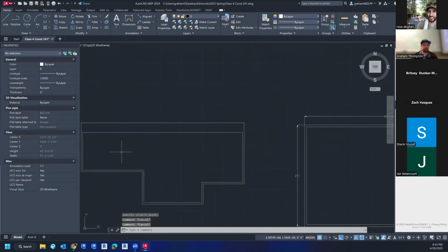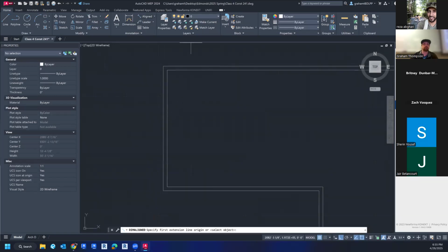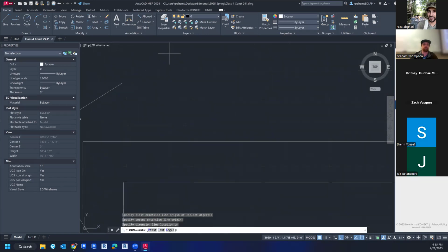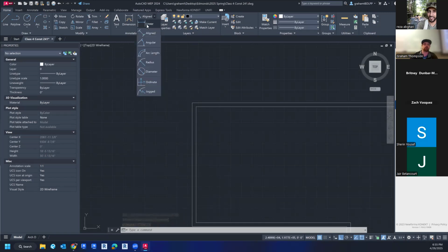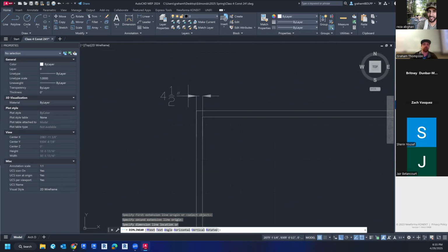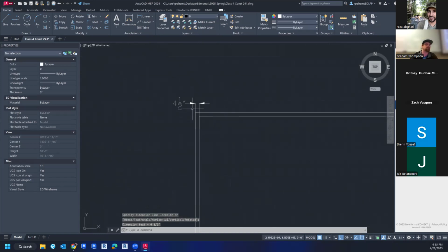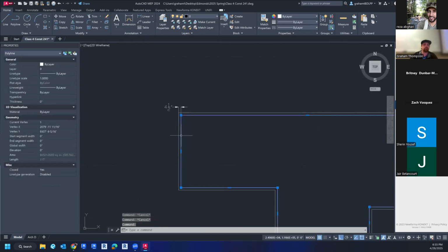Maybe I needed one wall specifically, and I'll take this and align dimension real quick between this wall and this wall. Oh, and it wanted to do a line between the points. I don't want it on the points. So sometimes when I've got two vertical lines, I'll make sure that I use the linear tool. Now I can go line to line and it'll show me exactly without trying to skew that dimension. So say this wall in particular, I wanted to be a 6 inch depth.